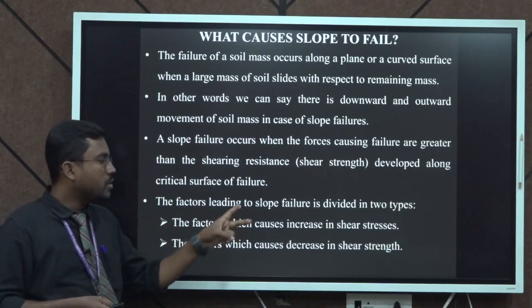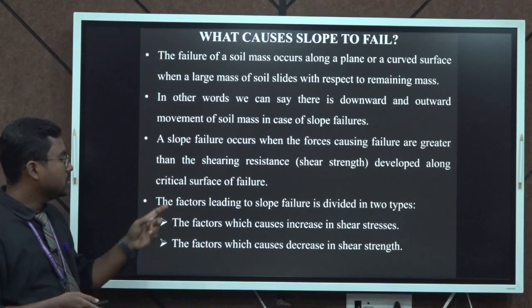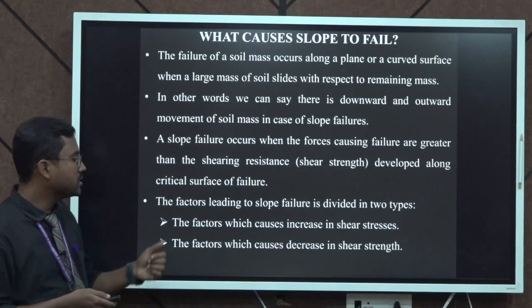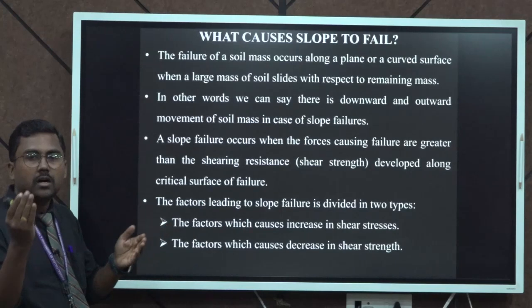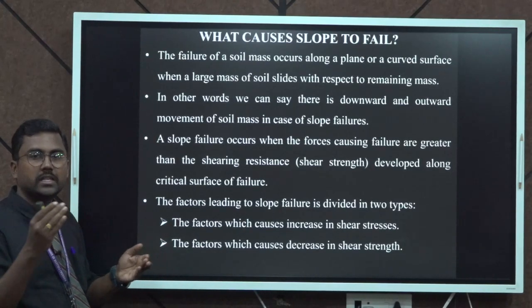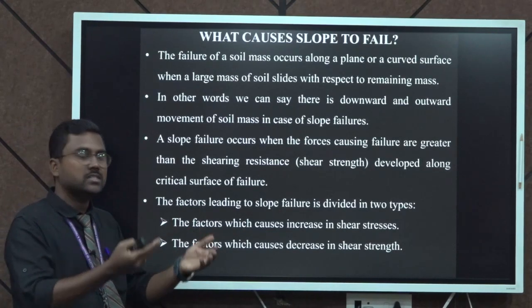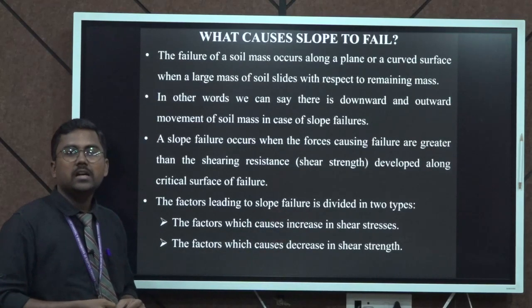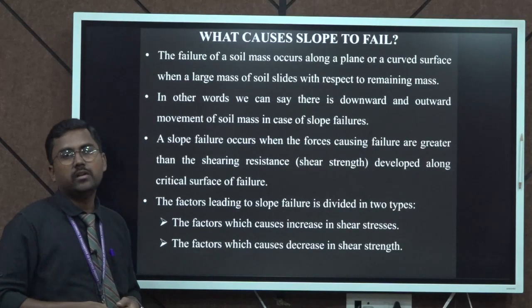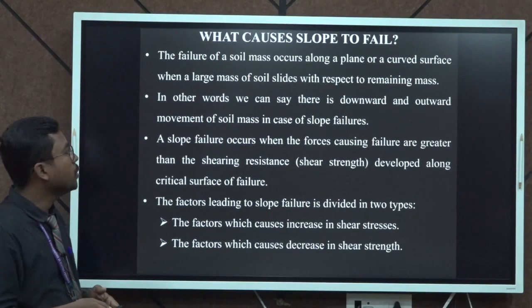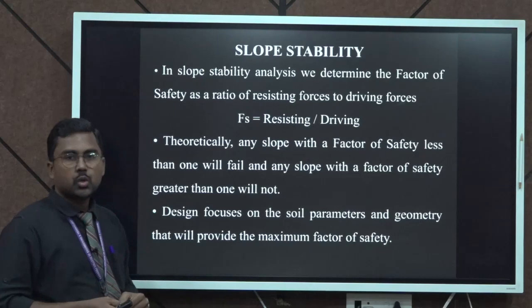And these are the two important factors we have to consider which lead to slope failure. That is, the factor which causes the increase in shear stress due to the increasing external load, and due to the increase in shear stress, the existing shear strength of the soil decreases. This causes the slope to fail. And this is slope stability analysis.